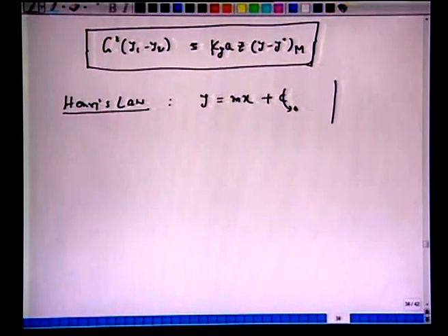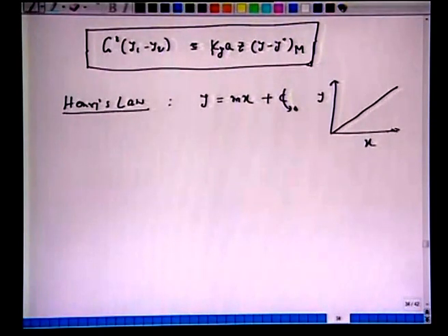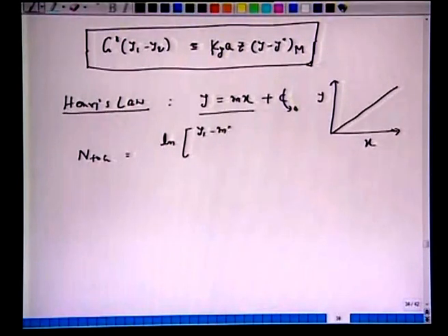When the intercept is very small, or at very low concentration with very small mole fractions in the gas phase, we can write the equilibrium curve as y equal to m x. In that case, NTOG can be shown to be obtained as a big expression, with y 1 minus m x 2, where m is the slope of this equilibrium curve, and y 2 minus m.